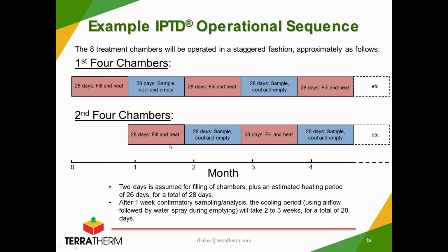And by treating rather than simply containing, we're eliminating long-term management at the location wherever the soil sediment may be stored and monitored. Finally, compared to kiln-style thermal desorption, this requires much less energy because of the amount of insulation around the heated soil, as I discussed, and the much longer treatment at lower temperatures compared to short treatment at high temperatures.